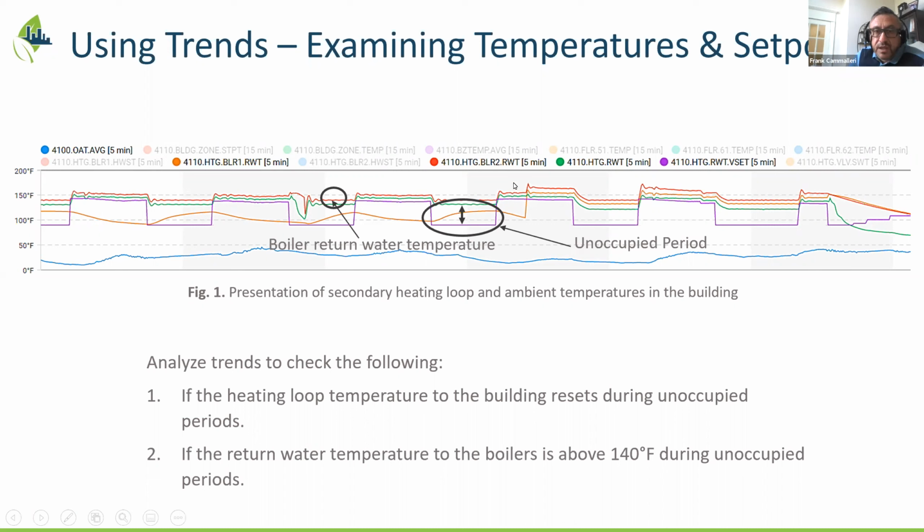Again, this is one view of it, and there was a big concern from an equipment maintenance perspective that the boiler return water temperature didn't go below 140. You get condensation, and these boilers are not condensing. So this is just one view about how you dig deeper. That first starts off with interval data. You're not waiting for the monthly bills to come in. Interval data shows you that there's some issue with gas increasing all of a sudden.